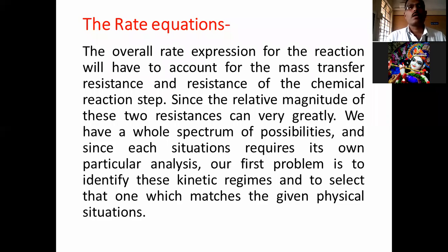Okay, it depends on the rate of reaction between the component of the gas and the component of the liquid. Suppose A plus B, A is the gas and B is the liquid. It depends whether it is an instantaneous type of reaction, or a fast type, or an intermediate type, or a slow, or an infinitely slow type of reaction. This reaction resistance will occur, means where does it occur: in the gas film, in the liquid film, in some plane, or in the main bulk of the liquid phase. This needs to be identified.